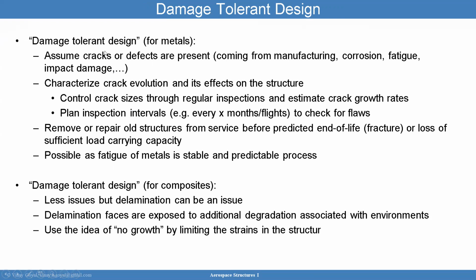Using this information, you need to plan for inspection intervals. Periodic inspections are implemented every many months or every many flights to check for how the flaws have progressed. Then that's going to help you determine whether you need to remove the structure from service or repair the old structure before the predicted end of life, or it may show that no damage has grown so you can continue to extend the life of the part.